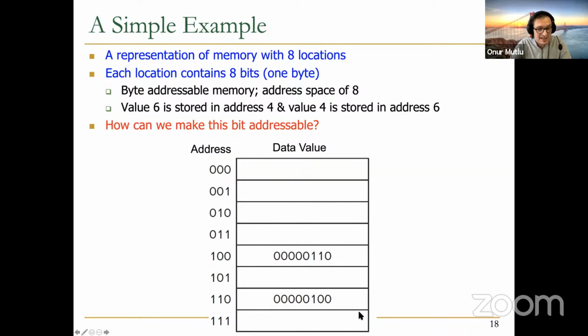So we get all of these in hardware, and then we select the bit that corresponds to address 1, which is this one over here. So essentially, you need a multiplexer that selects from these 8 bits and chooses 1 bit that corresponds to the bit address. So that's one way of making this bit addressable, and that's an important way, right?